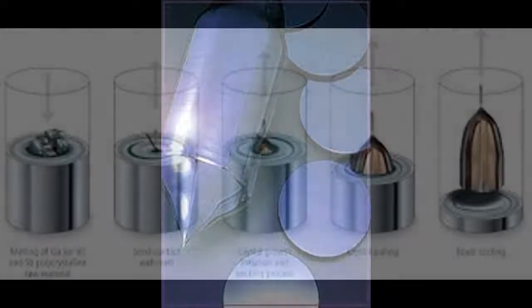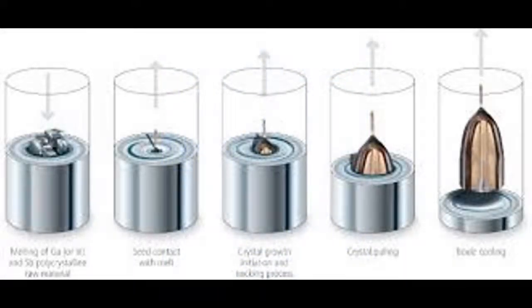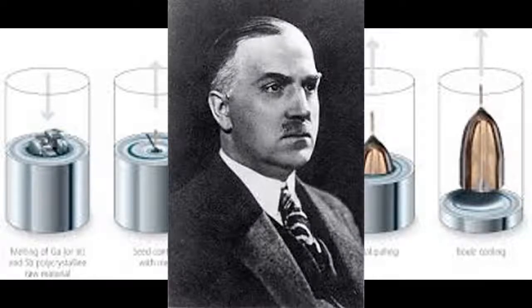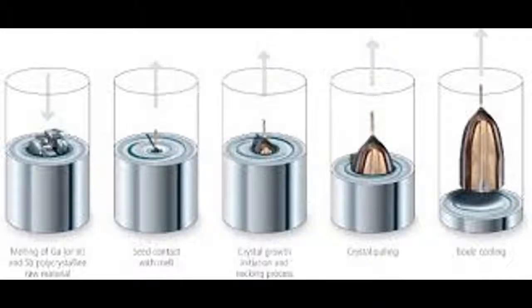One process for forming crystalline wafer is known as Czochralski growth, invented by the Polish chemist Jan Czochralski. In this process, a cylindrical ingot of high-purity monocrystalline semiconductor, such as silicon or germanium, called a boule, is formed by pulling a seed from a melt.